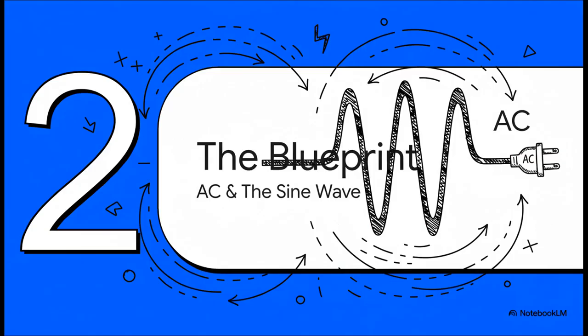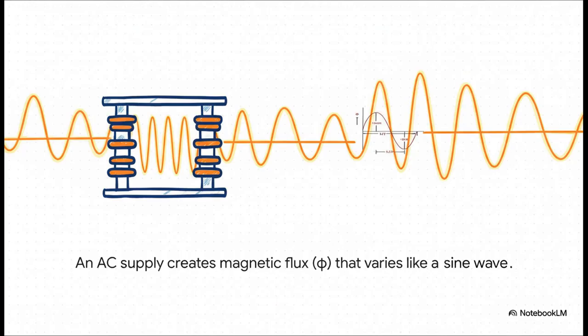So we need a changing magnetic field. And where do we get one of those? Well, we get it from an alternating current, or AC power source. You know, the stuff that comes out of your wall outlet. Its constantly changing nature is literally the engine that drives this entire process. And because our AC power supply alternates so smoothly, the magnetic flux it creates inside the transformer's core does the exact same thing. It produces this beautiful, continuous sine wave, building up to a maximum, dropping down to a minimum, and just repeating that cycle over and over.